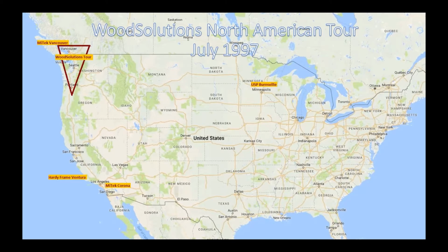The three areas that we went to had a lot of seismic activity as well, so the designs were governed in many aspects by that. And up in the northern side, particularly the Washington side, there's an immense amount of Douglas fir plantation, so Douglas fir is very commonly used over there. And SPF is the most common framing species for all other timber 4x2 framing styles anyway.